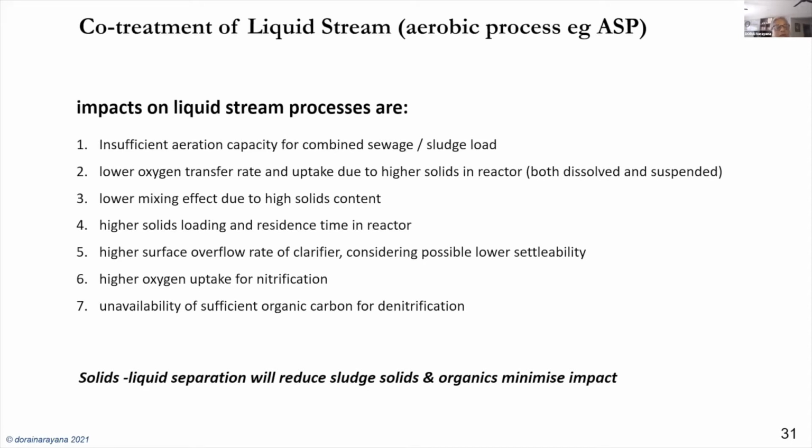And secondly, there could be a lower oxygen transfer rate because of the higher solids in the reactor, both dissolved and suspended, and that could cause the treatment facility to have less efficiency in terms of oxygen transfer. Mixing effect: usually the mixing in the aeration tank could be by mixers or through the aerators itself, creating a mixing. And because of the high solids which are in suspension, the mixing effect could be less, right? So this is another thing that is possible.